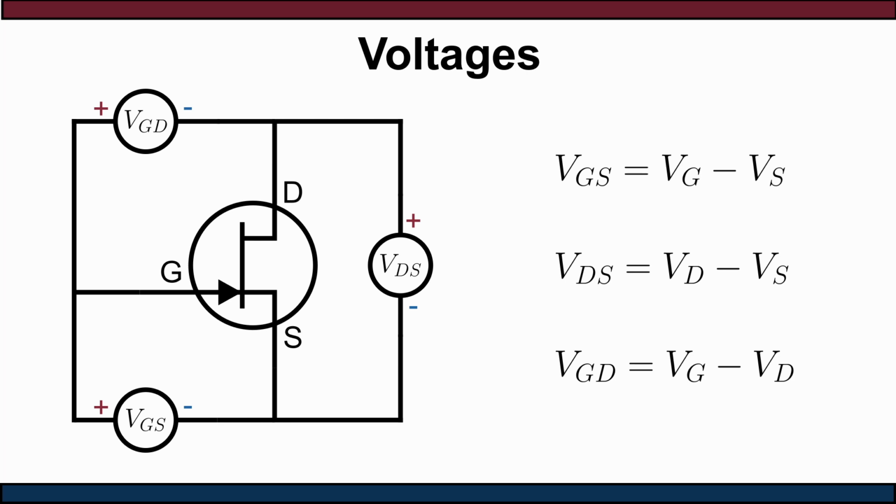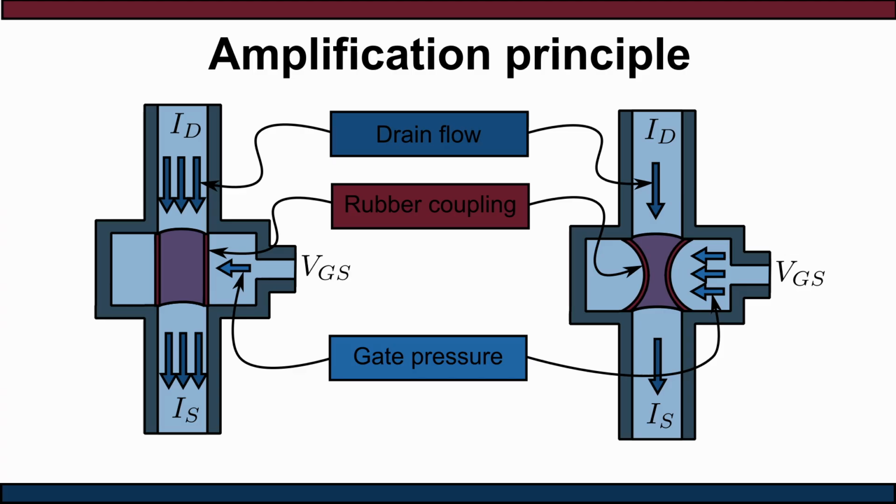Now we are ready to dive deeper into the processes in the transistor. From a practical point of view, the JFET transistor is a device that can control drain current via gate-to-source voltage. The amplification of a signal is based on this property. If we change the gate-to-source voltage according to the signal form, the drain current flowing through the resistor and the drain source path causes a voltage drop that can be significantly larger than the input voltage.